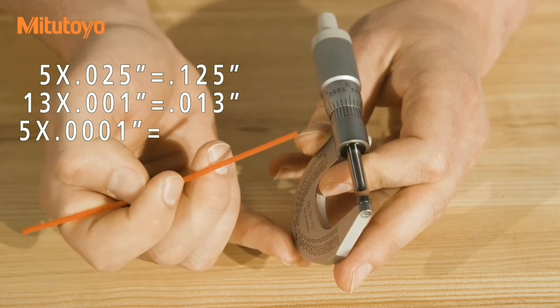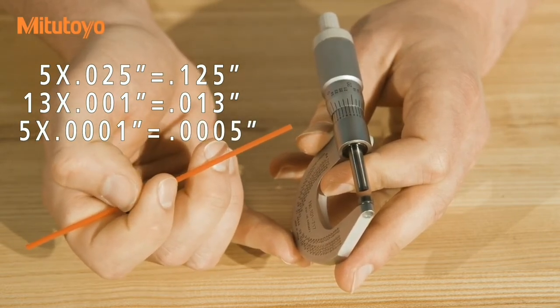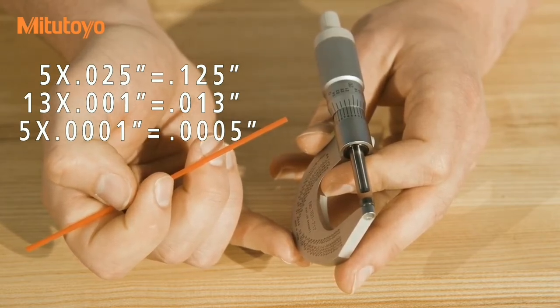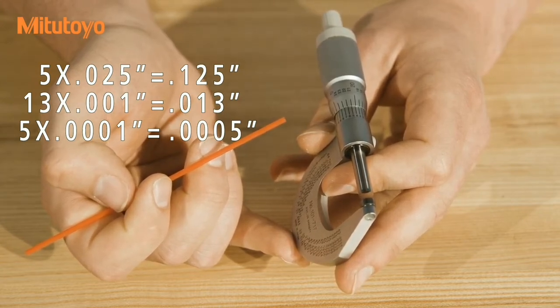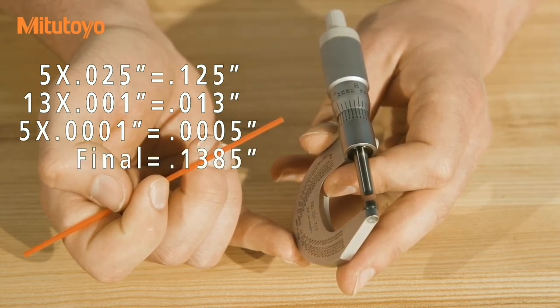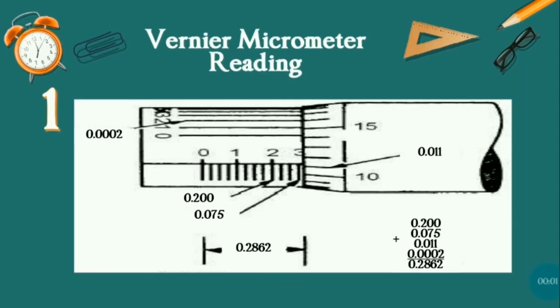In this case, that is 0.0005 inches or 5/10. The final reading is the sum of these numbers. So 0.125 inches, 0.013 inches, and 0.0005 inches for a final reading of 0.1385 inches. Okay, so now you already know how to read a Vernier micrometer.